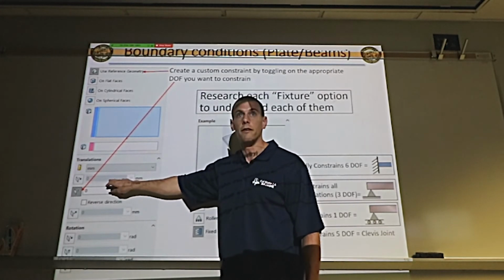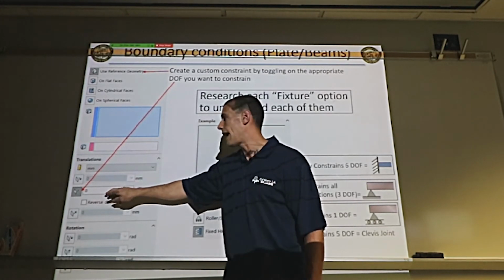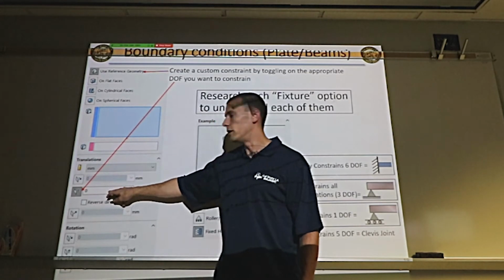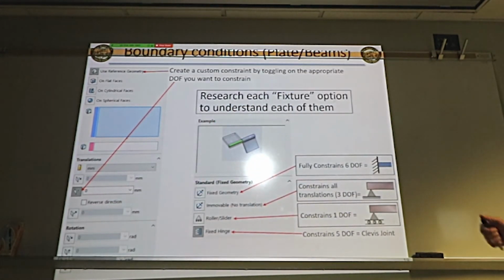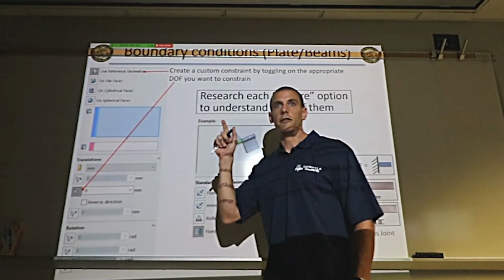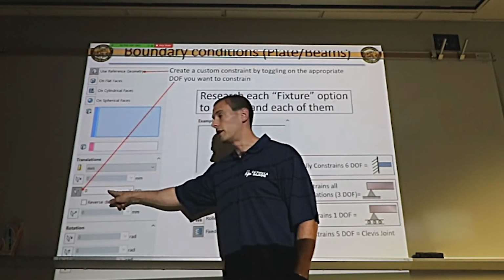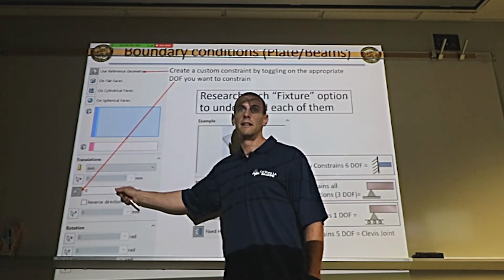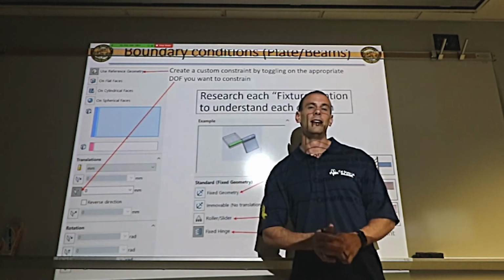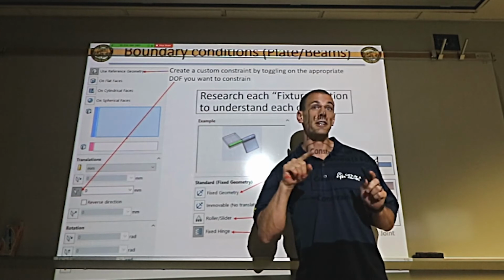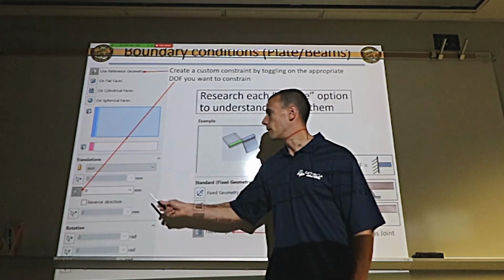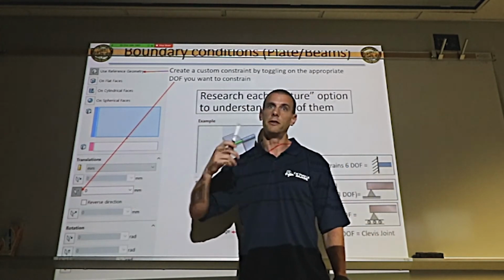You're saying it can't move. Like these are grayed out. This means it can move. You need to activate that cell, and you put a 0 in there, which means it can't move in that direction. You can remember that formula, right? Force equals KD. You can also put it, if you don't know what the force is, let's say you had a beam and you had some weight on it and you had no idea how heavy that weight was, but you had a measurement of the deflection of that beam. You can put the deflection in instead and it'll give you the stress.